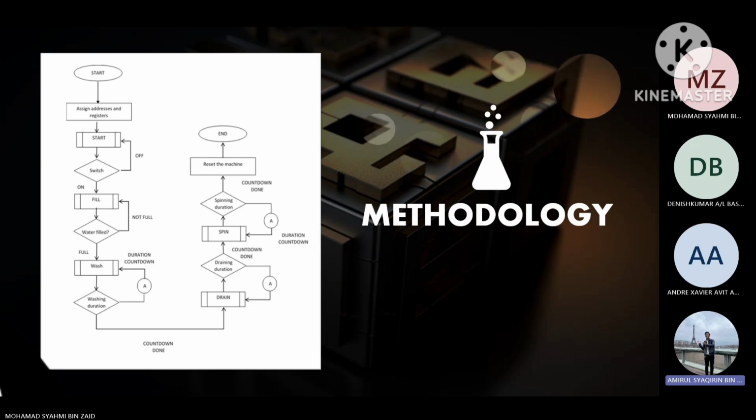There is code that shows FILL on the 7 segment display, as you can see in our report. During the filling operation in the fill subroutine, the water level is checked using a sensor, represented by a slider for the purpose of the simulation, also shown in the report. When the tank is filled, the software will go to the wash subroutine automatically, and the operation of the motor here is represented by an LED simulation, as shown in our report also.